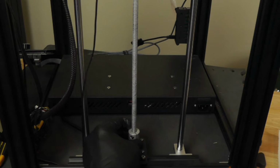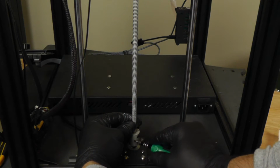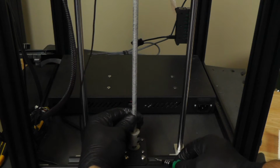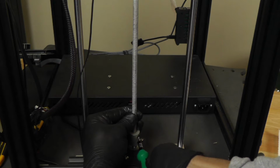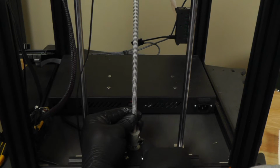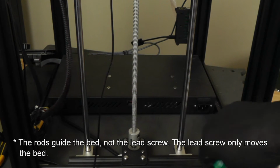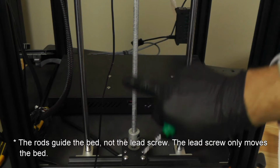Let's first attach this. To do this properly, I don't necessarily like it to sit directly on the axle of the motor. I'm going to actually raise it up just a little bit, and then I can tighten it. That just gives it a little wiggle room, as well as protects it from vibration from that motor potentially. Because after all, the whole point of the leads on here is so that this is not actually directing your plate, this is just controlling the motion.